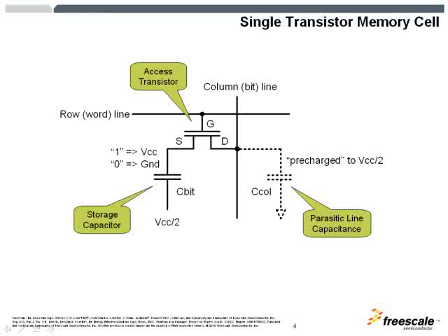Before the transistor is turned on, the column bit is pre-charged to VCC/2, and the line is momentarily removed and left floating. However, the parasitic line capacitance will keep the voltage that is on the line, and when the transistor is turned on, the charge on the capacitor will either increase or decrease the VCC/2 voltage on the column line.